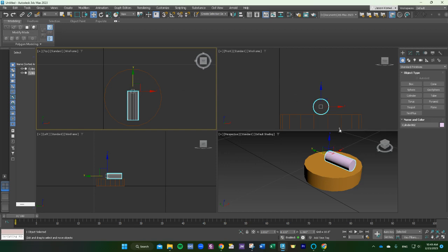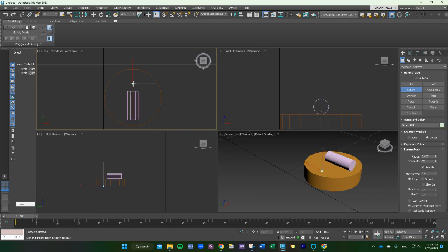Okay, so from there, let's put the sphere in. So I'm going to grab a sphere. I can do it from here, I guess. And remember, spheres draw from center out. So draw a sphere, and this is going to be, let's see, a 1-inch sphere, so we'll make the radius a 1/2 inch, so 0.5, okay? And we want to drag this down so that the sphere is entering the cylinder here, as if it's part or welded into there or drilled a hole in there.